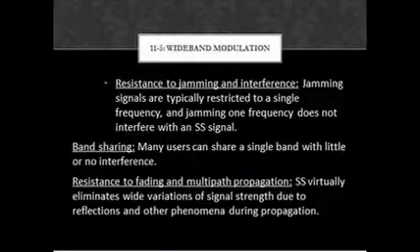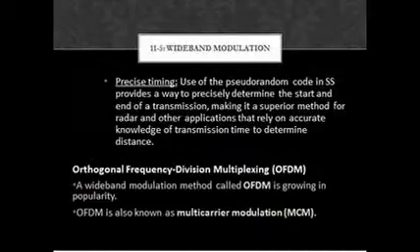Modem operation. The data to be transmitted is stored in the computer's RAM. It is formatted by communication software installed on the computer. It is then sent 1 byte at a time to the modem. Most data transfers and operations inside a computer are parallel. But since long-distance data communication is done by using serial binary data, the modem's first job is to convert parallel data to serial data.